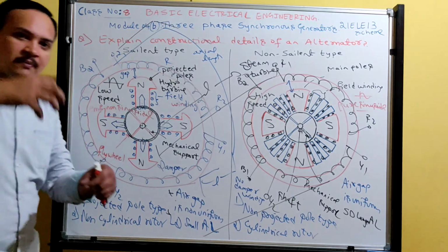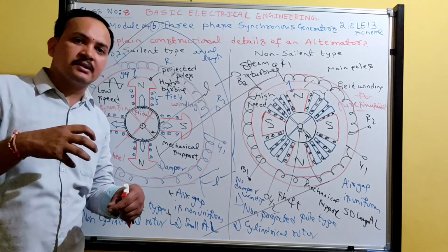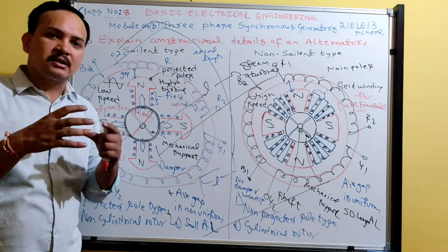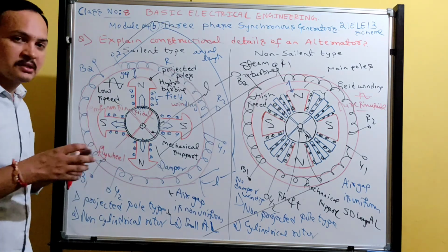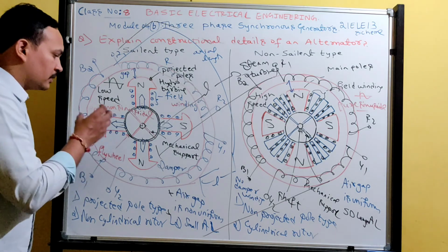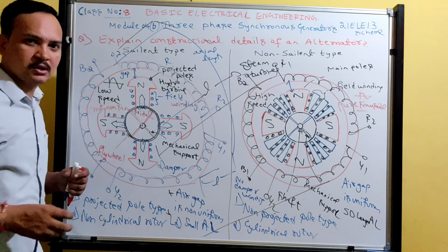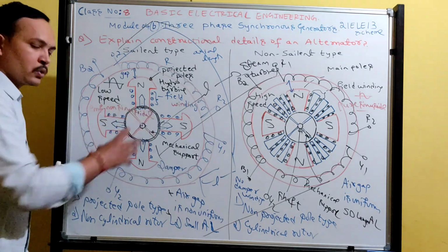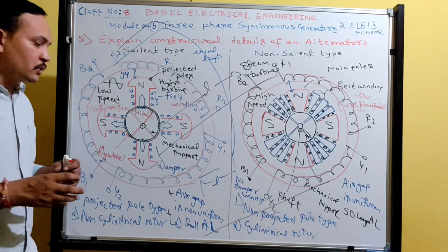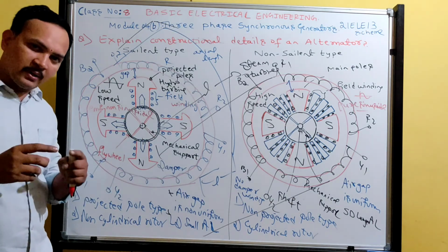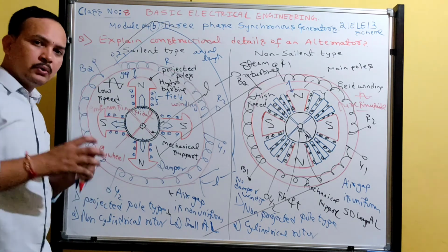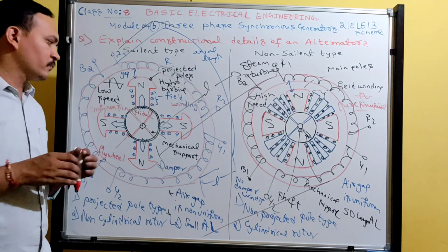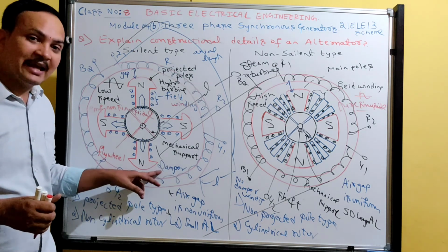If the water pressure on the turbine suddenly increases, the turbine will get slight vibrations. Since the turbine starts vibrating, the turbine shaft coupled to the rotor shaft of the alternator also gets vibrated. So whatever vibration effect is on the turbine will also occur on the alternator. In order to reduce those vibrations, we have to use damper windings.